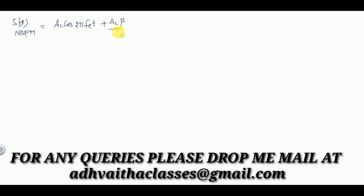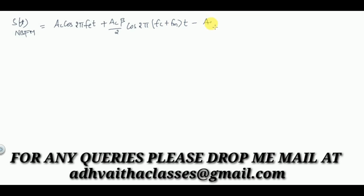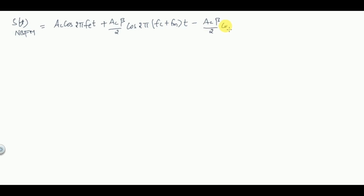So now we have seen the standard time domain equation of NBFM signal. Narrow band frequency modulated signal is given by Ac cos of 2 pi fct plus Ac beta by 2 cos of 2 pi into fc plus fm into t minus Ac beta by 2 cos of 2 pi into fc minus fm into t. Okay, so this is same as AM, yes or no?